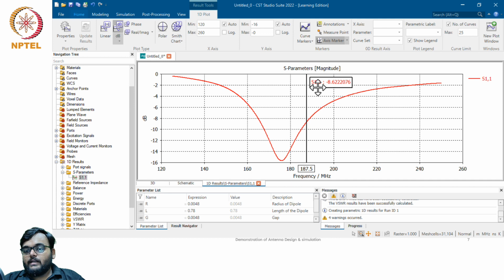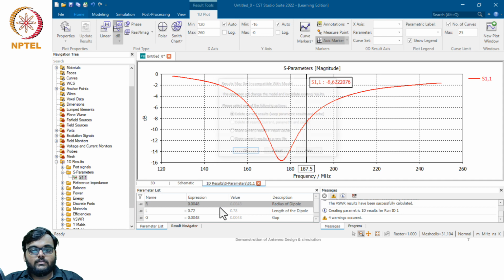So because of that I took a wider area. But what we are seeing is the frequency is at the lower side. So here what you can do, you can change the length to say 7.2, then update it, press OK,